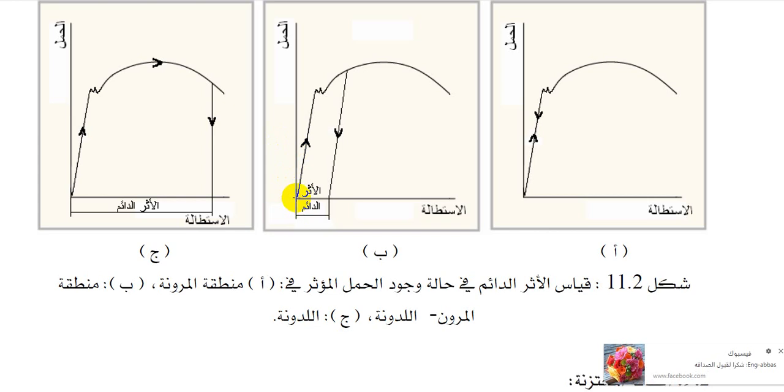The elastic line runs upward to the upper yield point, then necking, then the ultimate tensile stress and the fracture point, at which, just like we said before, the specimen will be split into two halves as a result of the load distribution to the shoulders.